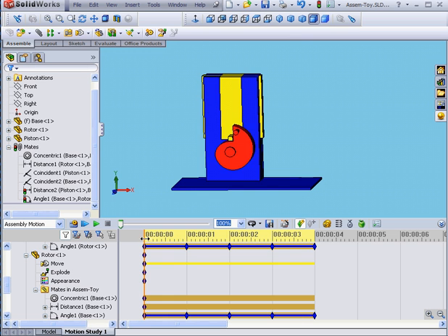For the initial position, if I'd used this face, for example, it would have made the initial angle 90 degrees. I'd need to have calculated starting from 90 degrees, then 180 here, 270 here, 360 here, and back to 90. Unfortunately, this probably would have confused SolidWorks, and we would have ended up with some similar inconsistency in our animation that we just saw when I changed the value from 360 to 0 degrees. You need to watch for these types of issues when using angular mates.